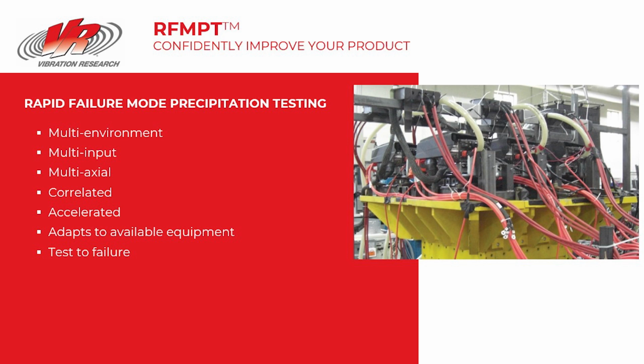This picture shows a good example of a full-blown RFMPT test setup for a complex DC to AC inverter for an automotive application. This test used a simultaneous 3-axis hydraulic rig for vibration tests that fits under a thermal hood, which for clarity is not shown in the picture. The thermal hood can use either focused liquid nitrogen or conventional refrigeration to achieve desired thermal ramp rates. You can also spray 5% sodium chloride to simulate corrosion environment.